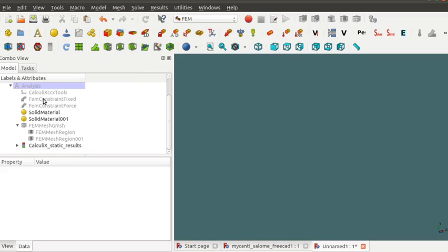Up to this meshing and creating this INP file, I will show the topology optimization process using the CalculiX solver. I will use the .inp file format. Everything up to creating this INP format is included in the pre-processing stage from the FreeCAD point of view. Next, I will show how to generate similar pre-processing steps using the open source pre-processing and meshing package called Salome.